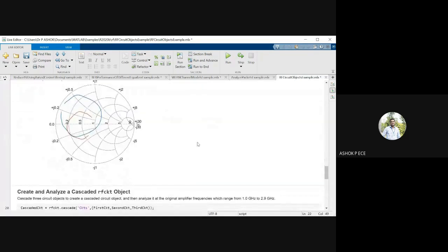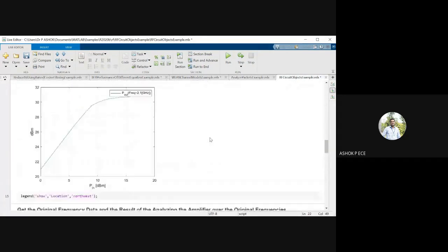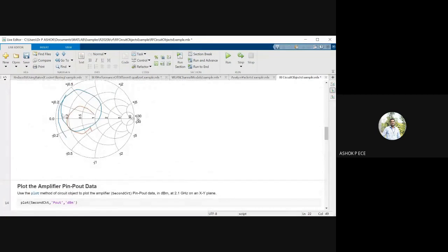Previously, you see, this blue circle is containing this one point, but the red circle is slightly away from the one point, so the amplifier is unstable. In the previous graph, same thing: the blue circle is encircling this one point, and the red circle is slightly touching this one point. If you extend this red circle, it's slightly touching the one point.